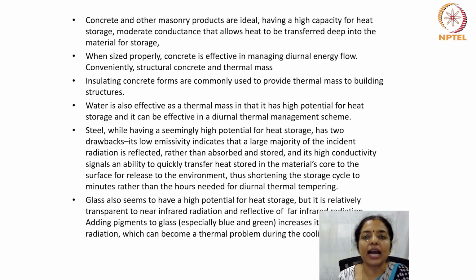Concrete and other masonry products are ideal as they have high capacity for heat storage and moderate conductance that allows heat to be transferred deep into the material for storage. When sized properly, concrete is effective in managing diurnal energy flow.